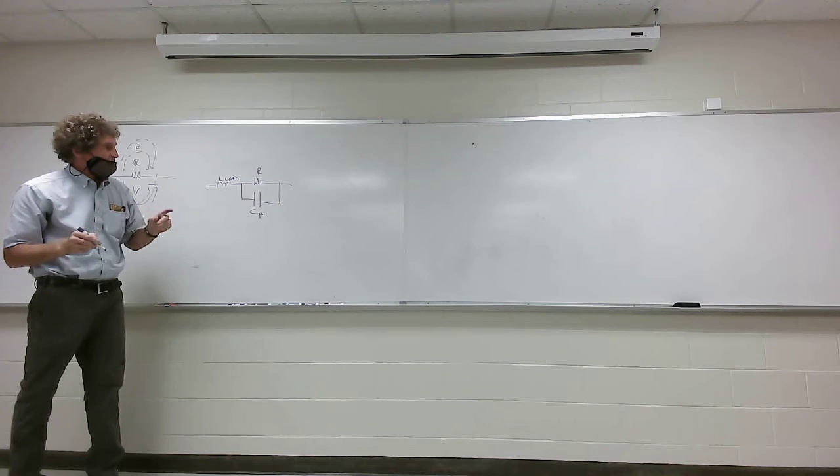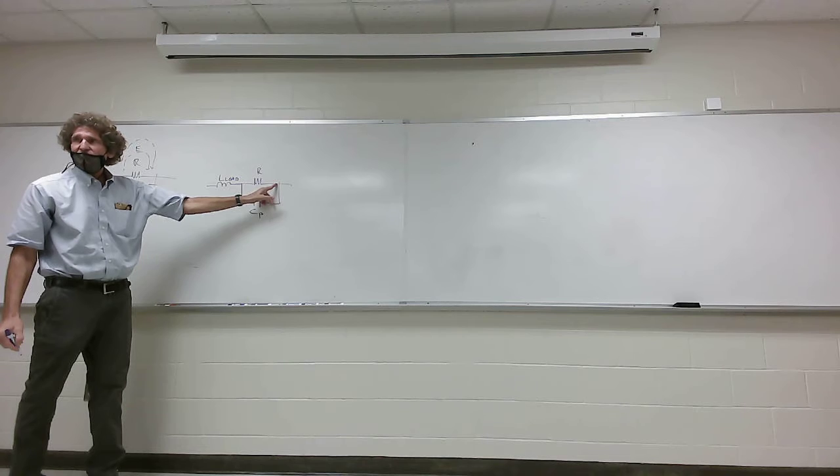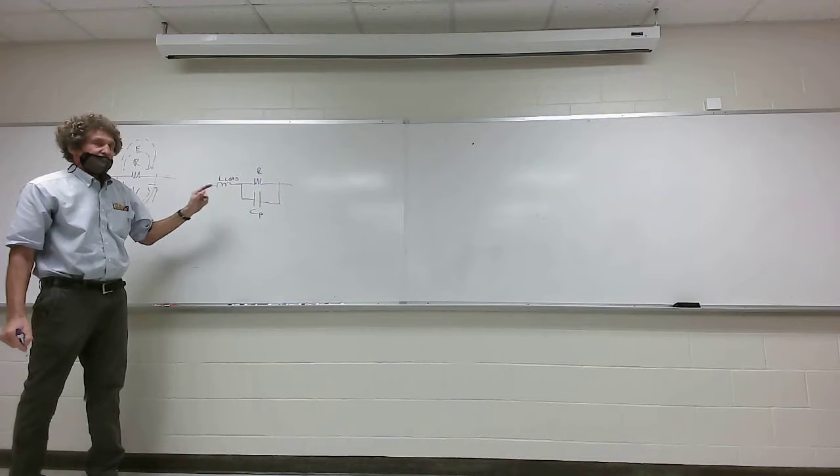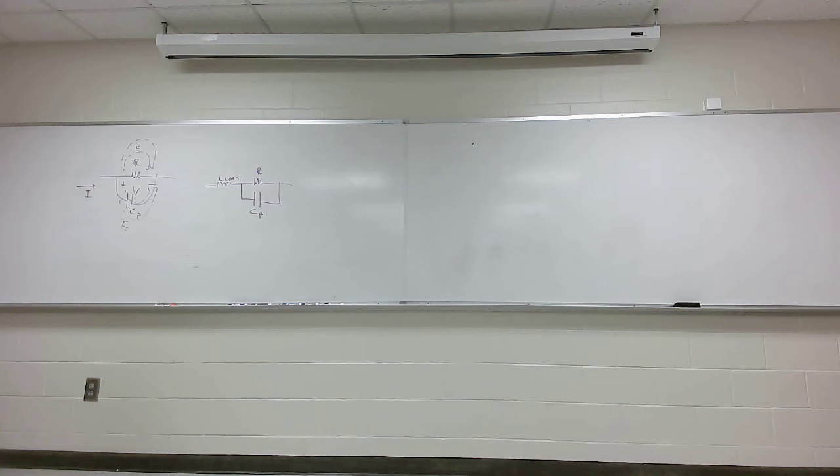Now in Whitworth's book, he'll talk about how there could be an internal inductance there. But usually that's so insignificant it's not worth talking about, if there's any proper design. Mainly it's the leads. Have you been told when you built circuits to cut the leads as small as possible before you solder them? Remember that. If you ever have to do any high frequency design, especially your first time, if you're building anything for a radar circuit, anything over a gigahertz, get your lead lengths as small as possible. And one other thing, apply the least amount of solder necessary.